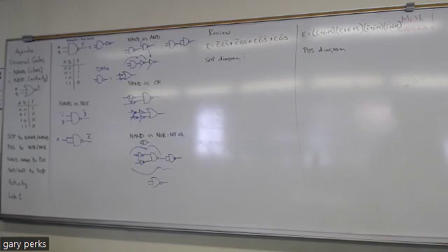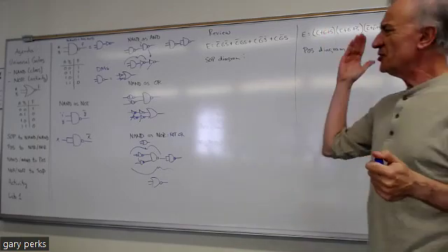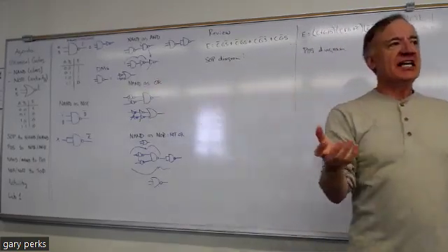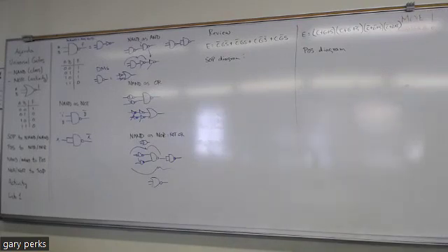Well, back when I took this class, and like I said, up until about 20 years ago, those types of ICs, those FPGAs, didn't exist. So you would have individual ICs, and these individual ICs would only have one type of gate on them. Like you could buy an IC that only had inverters. You could buy an IC that only had NAND gates, only OR gates, and so on. Well, if you could do your design all in one gate, that means your purchasing department would only have to buy that one type of gate.